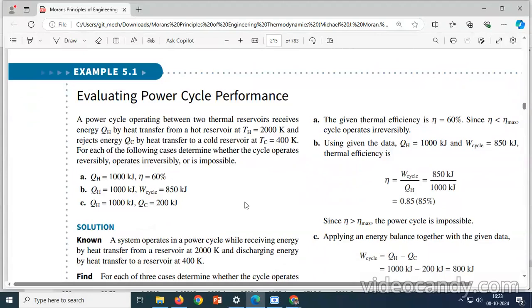When the heat is transferring from a lower temperature sink to the higher temperature reservoir, work cannot be zero. So there should be some work required when you transfer the heat from low temperature to high temperature. The examples given are one is heat engine, other is the heat pump, transferring the heat or energy from low temperature to high temperature, or also they have given the name as pumping the heat from lower to higher region. That is also not possible without any work done on the system. So taking those two cases, here a problem is solved.